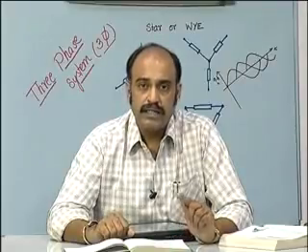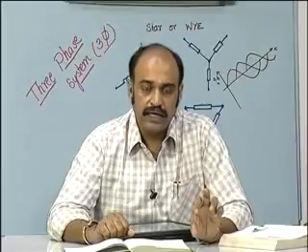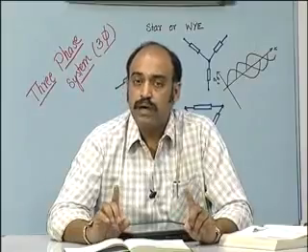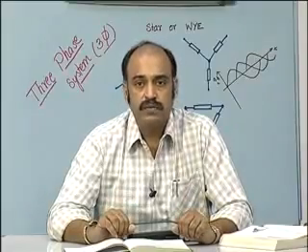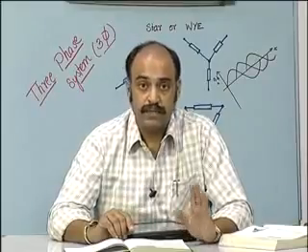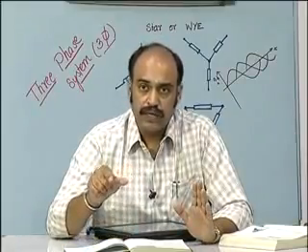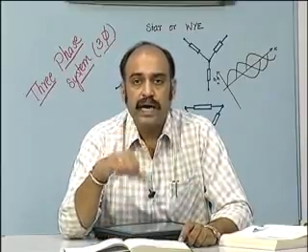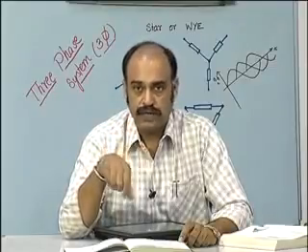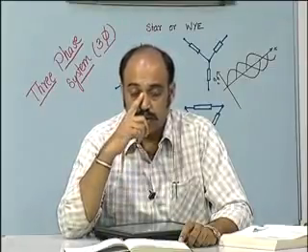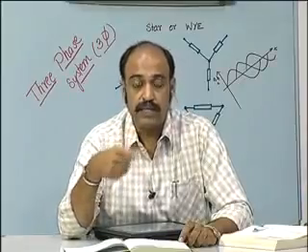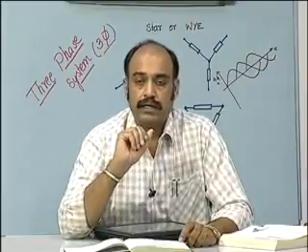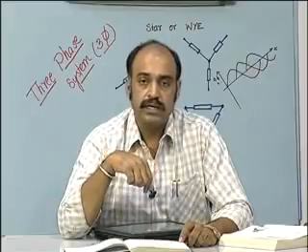In order to balance the line currents, that is, the line currents should have the same effective values, 120 degrees displaced from each other in the spatial coordinate system, we modify the delta circuit by including two reactive loads in the other two phases. So, we have a resistive load, which is the active power drawn from the mains. It is still only the active power which is drawn from the mains, but we add a capacitance and an inductance in the other two phases